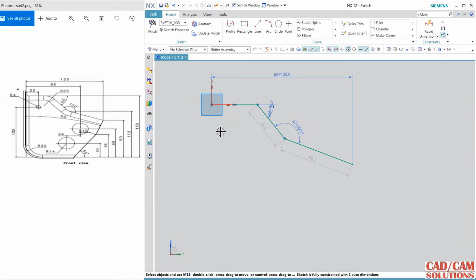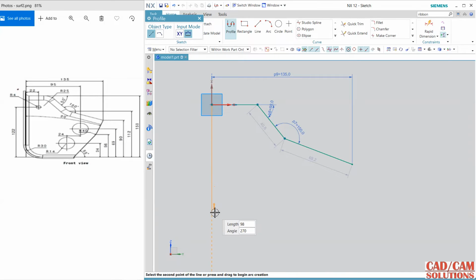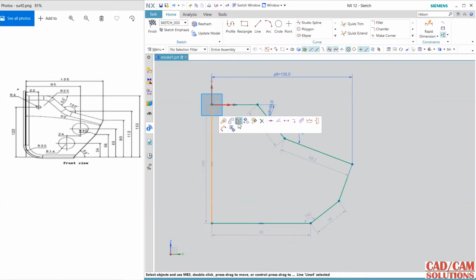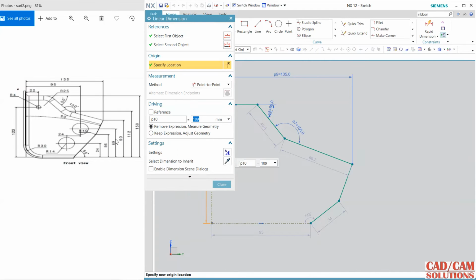Okay, and for the rest of the options I'm going to create two reference lines. See here, one and two, and again one line and then taper, one line and then taper, which will match to this end. I don't want this, so I'm changing this line to reference, so both lines are reference lines. So this vertical distance is 150, so change it to 150.